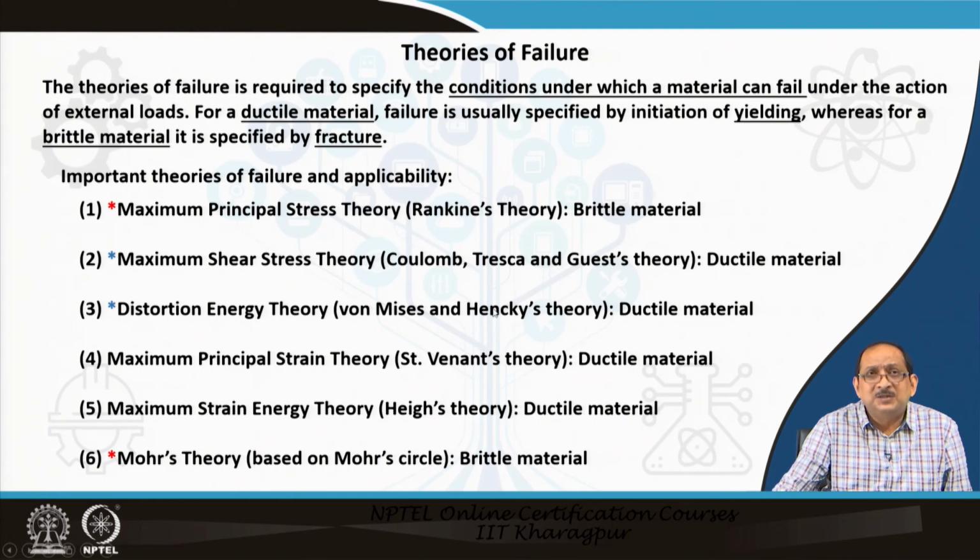So, within this set of 6 theories, maximum principal stress theory and Mohr's theory are popularly applicable for brittle materials, and maximum shear stress theory and distortion energy theory are applicable for ductile material.